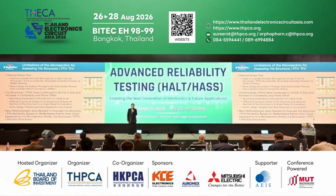It's not that difficult to do on big vias, big PTH, but with small vias, especially these days, with everybody going AI or data center, everything is going smaller. So it's very difficult to stop at the very center of the microvia, making microsection very difficult to do.